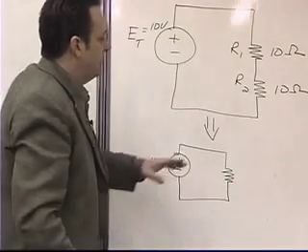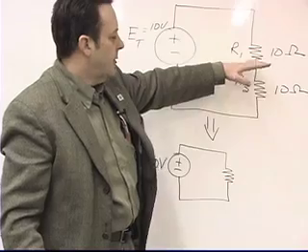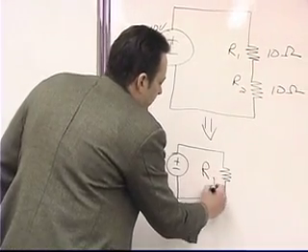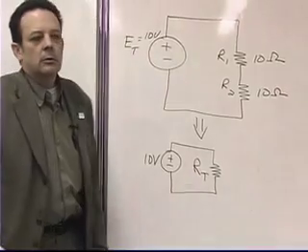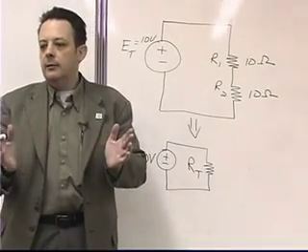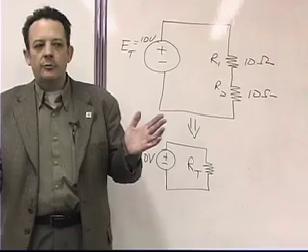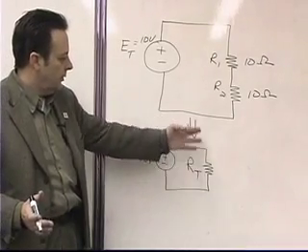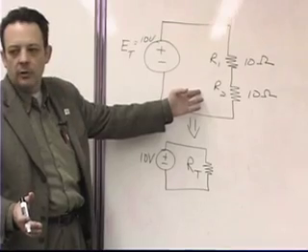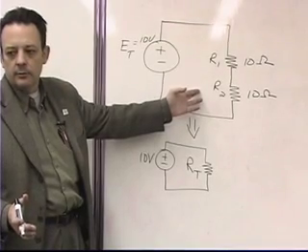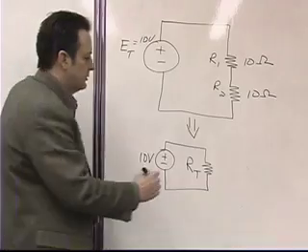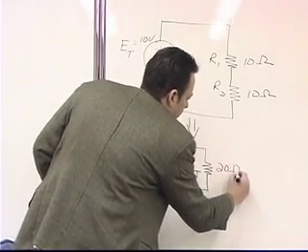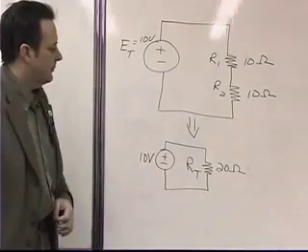And when we have series resistors and we want to find out what the total resistance is, we just add them like money, right? It's called algebraic addition. So what would the total resistance be of the equivalent circuit of this unloaded voltage divider? 20 ohms. So it would be 10 plus 10, or 20 ohms. Okay?